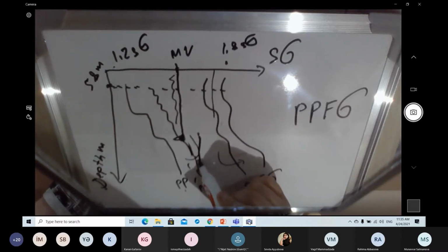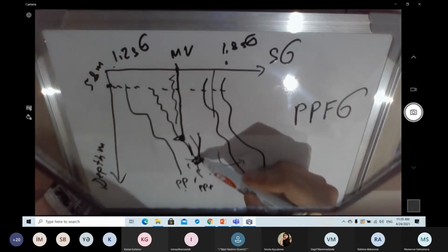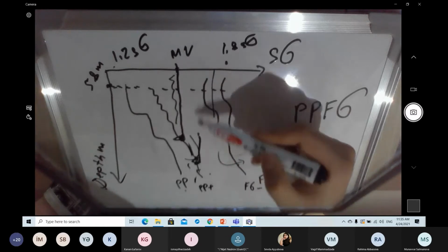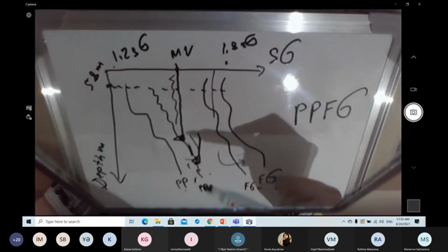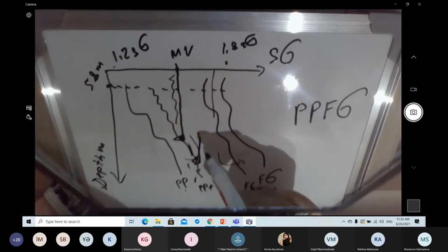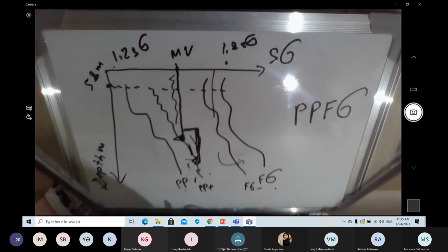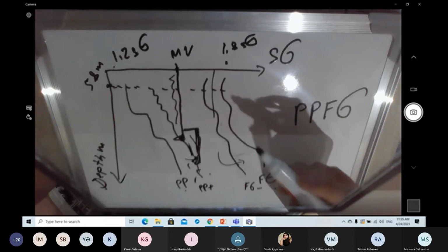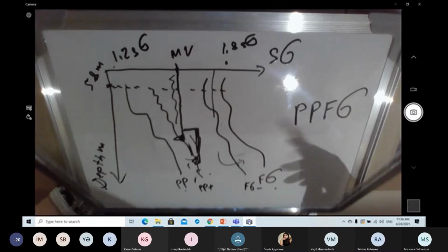We will need a higher mud weight, and we come here again and stop because we reach our pore pressure plus safety factor, right? You see this column is probably not long, and if it is not long, we don't want to go to the surface because it is financially expensive and it will take a lot of time to run the whole casing and also to cement this casing. That's why, if operating companies have such a short section interval, they run a liner. So we also highlighted the liner here. That is the way we decide which intervals we will have, how many casings and how many liners we will have.